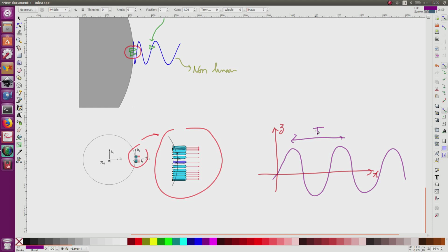So now, when the inertial unit is not perfectly initialized, we may find a different trajectory that is consistent, and the inertial unit can take the wrong one. In the case where the linear approximation is realistic, such as when I'm here, the inertial unit will return some unwanted oscillation, corresponding to a period of 84 minutes, the Schuler period.